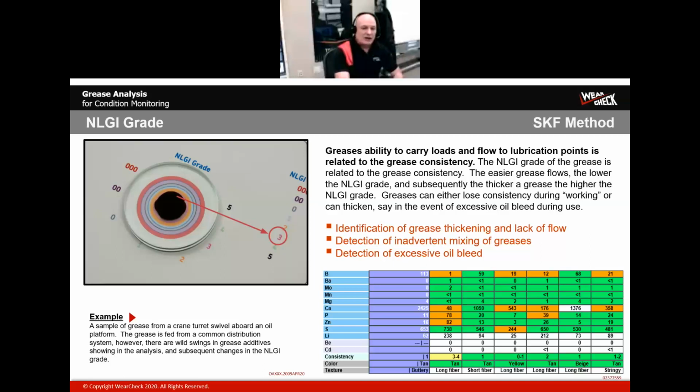And I was having this discussion with my internal diagnostics group a few weeks ago. I was showing this presentation to them, and we were talking about what are some of the parameters or tests we would use to condemn greases. And generally, the consistency is the one test that is really a good indication of when something is going dramatically wrong with your grease.